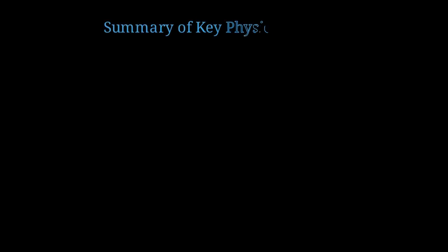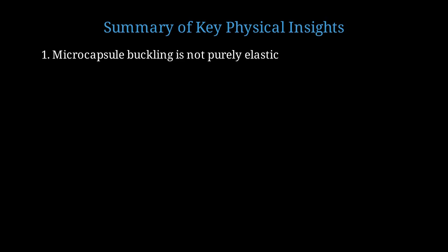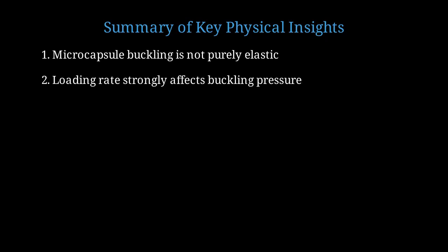Let me now summarize the key physical insights we've gained from this lecture. First, microcapsule buckling is not purely elastic. Time-dependent viscoelastic effects are crucial and cannot be ignored. Second, the loading rate strongly affects the buckling pressure. Fast loading gives higher thresholds than slow loading.